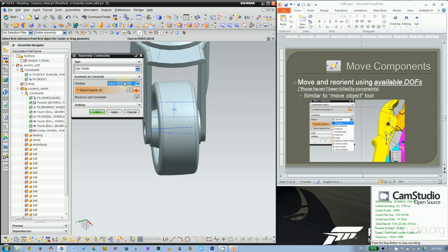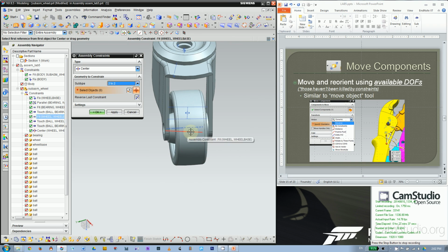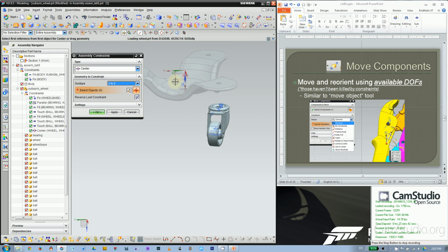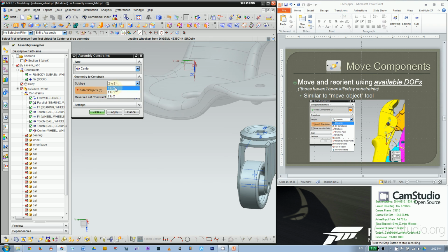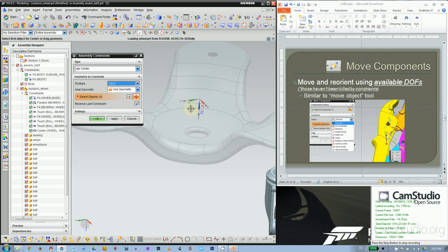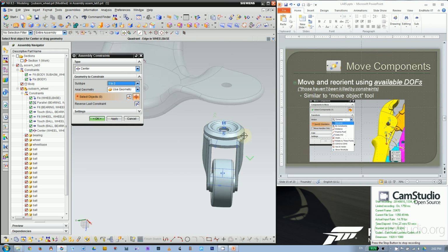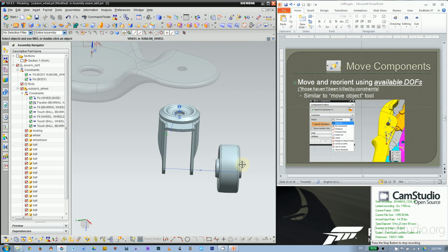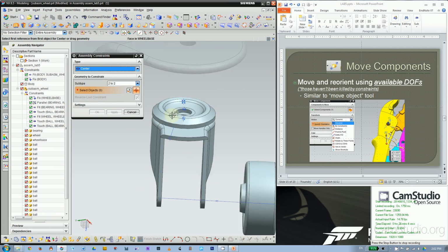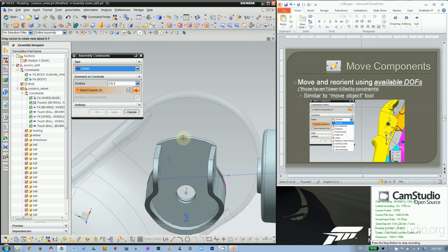Okay, so now you know how to apply the center constraint with the 2 to 2 subtype. And if you have only one thing, let's say a y-axis or xy plane, let's try 1 to 2. Okay, so what is the 1? There's nothing here. We can try here, center. What's the 1? Let's find something.